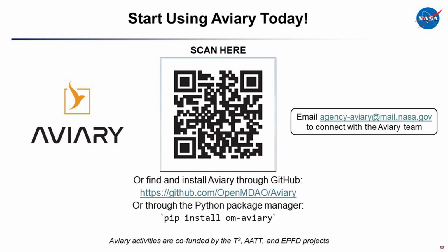So Aviary has the capability of doing cycle design if you bring in an external tool. For example, the TTBW model, we had a PyCycle model doing cycle design. We also have, the ATT group has a rudimentary wrapper for MPSS. MPSS is so freeform that you can't have a one-size-fits-all wrapper, but they have a fairly genericized one too. So you can use that to do turbine design within Aviary, and you can do your cycle design as part of the overall aircraft optimization.